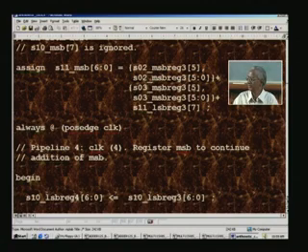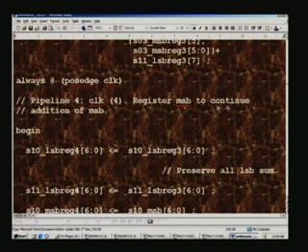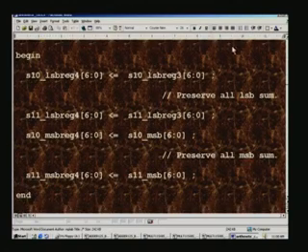So at the next clock edge we are going to register the MSB to continue addition of MSB, and this is at positive edge of the clock, and this is the clock 4. Here we also preserve the LSB which we have added earlier, because finally we had to put them all together, MSB, LSB, and that is the reason why we are preserving here. So all these are preserving the LSB, and this is preserving the MSB.